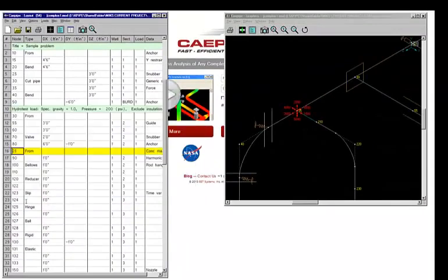So to summarize, we have increased the number of thermal loads to 10 and the number of wind loads to 4. With these, you are now able to define up to 100 load cases, or 2 less than 100.